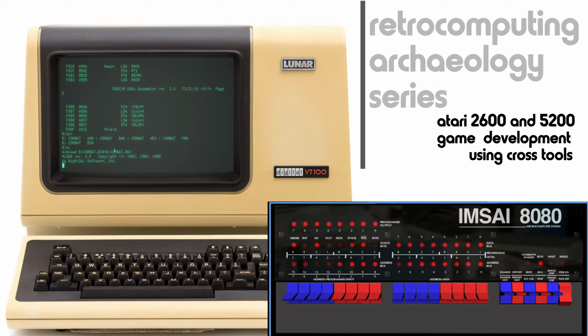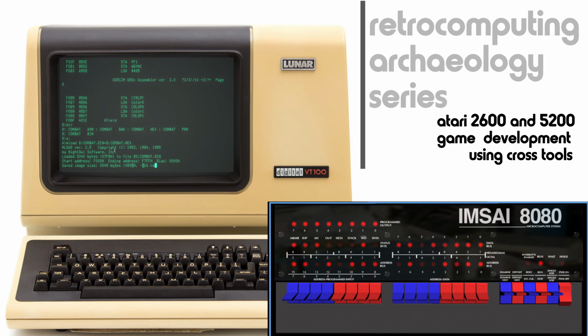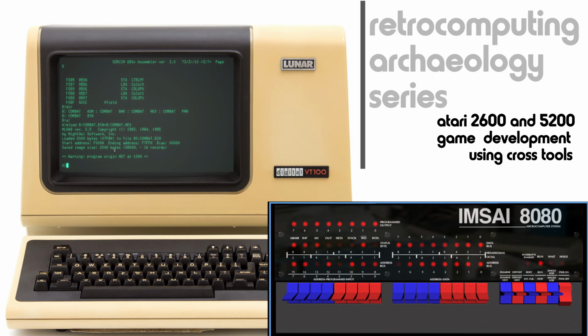So we do this, it creates the file, and it gives us some statistics about the file here. It's saying, okay, start address F000, ending address F7FF. There's no bias because we're not shifting it up by any number of bytes. We've wound up with a file that's 2048 bytes long. That's exactly 2 kilobytes to fill a 2 kilobyte EEPROM. 0800 hex bytes, 16 records' worth.